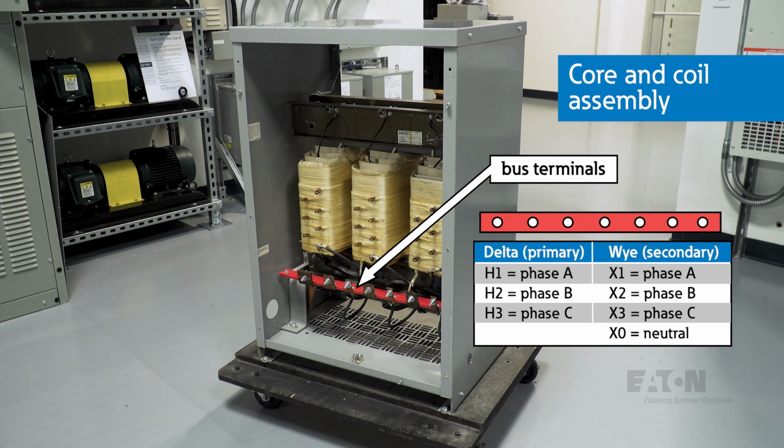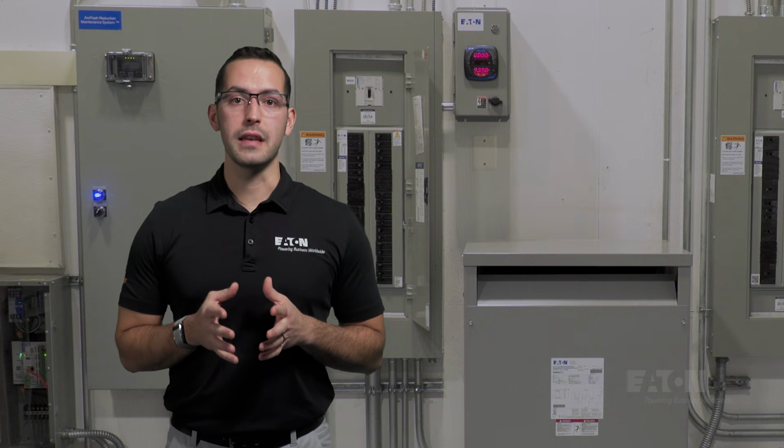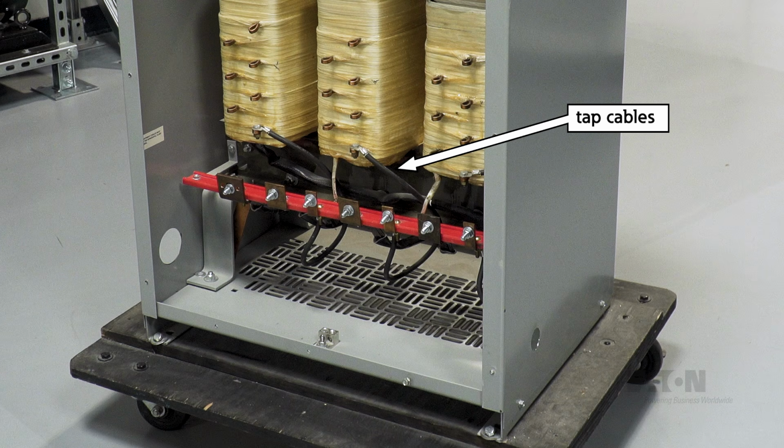These terminals provide the connection point for incoming cables on both the primary and secondary of the transformer. A three-phase delta power connection will include 3 terminals, while a three-phase 4-wire Y power connection will include 4 terminals. One set of terminals is connected to their windings through the small black cables seen here, known as tap cables, as they are connected to the transformer taps.